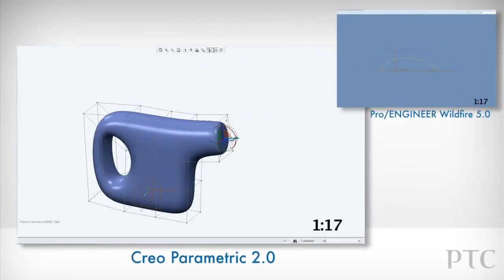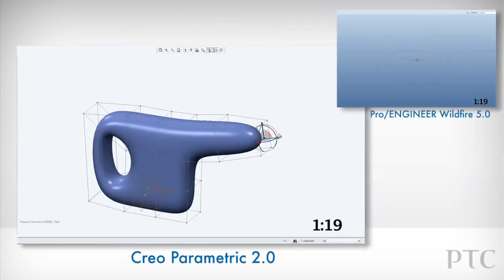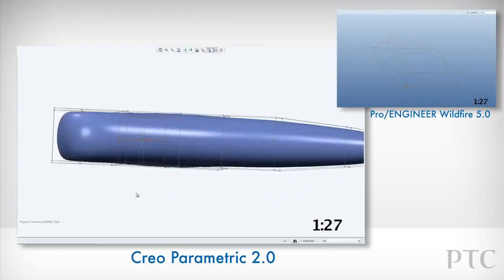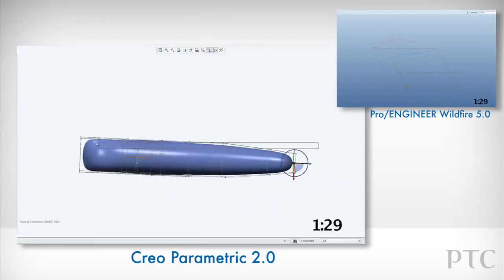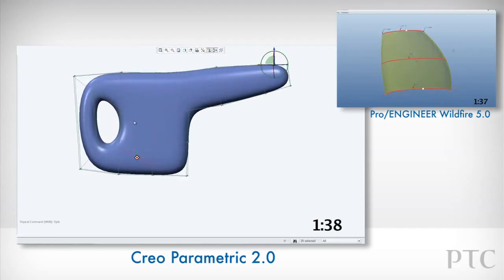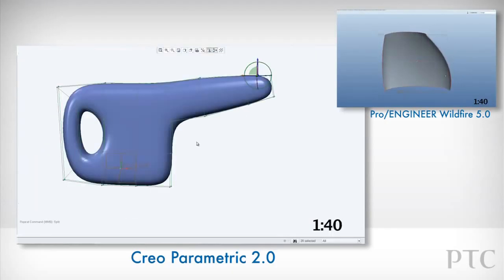Back in Creo Parametric, we're going to create the neck of the watering can. We can add geometry and then use the split command to add finer control on the way. Since we're designing a product that's symmetrical, we can use the mirror command. After selecting the mirror plane, half of the control mesh disappears. Any change that we make along the neck is mirrored to ensure a symmetric part. It's also possible to locally break mirror dependency.